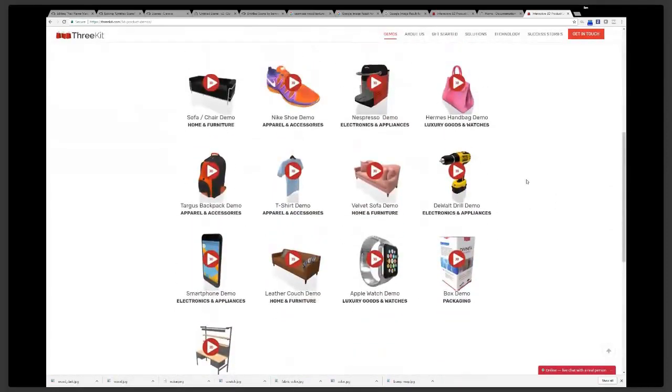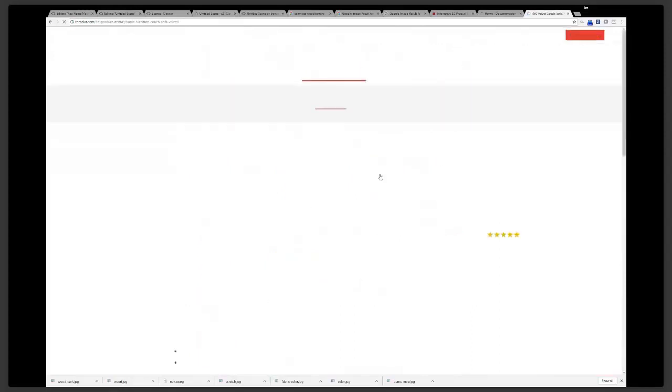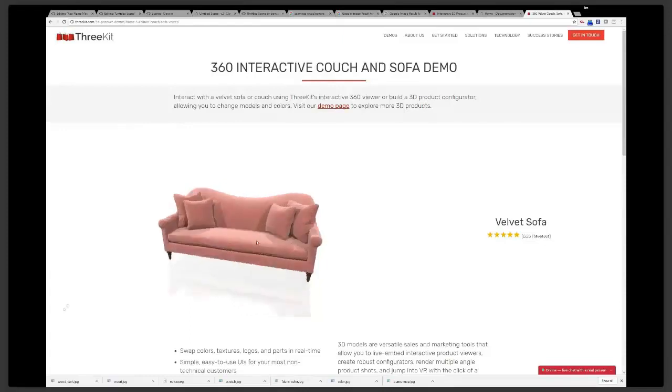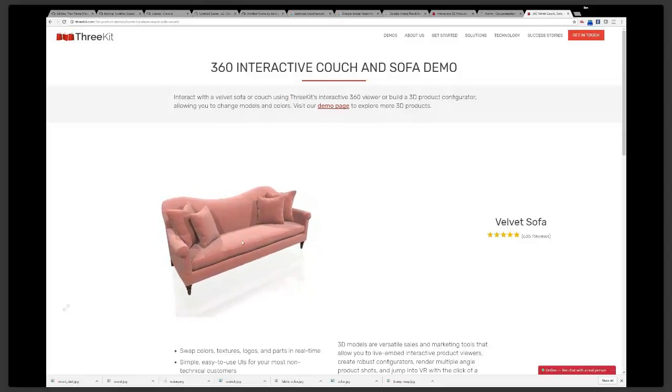The last thing you can do, if your furniture isn't dynamic, is pre-calculate some lighting and import that as AO maps. We also support baked light maps as well. I didn't go into those workflows; it's a little involved. This one is not fully soft shadows, but you can see that it does get darker because we have multiple different shadows overlapping.